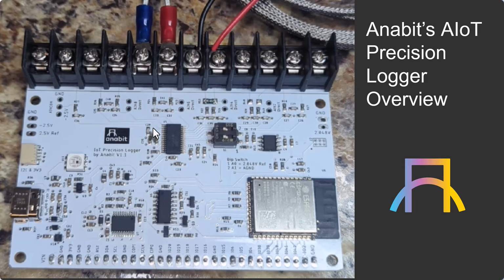The ADC has a built-in 2.5 volt high stability voltage reference, but we offer an optional second external reference right here that's even higher accuracy, at 2.048 volts, and it's even higher stability over temperature changes. Once again, that's optional, and if you get that, it'll come with this DIP switch where you can route the external reference to the ADC, or you can disconnect it if you want.